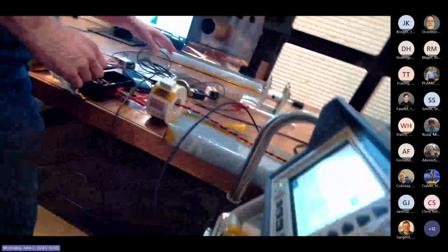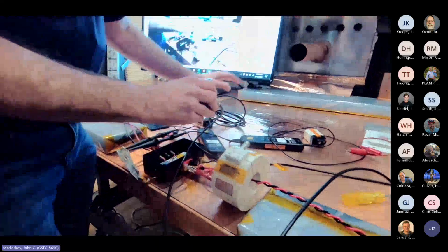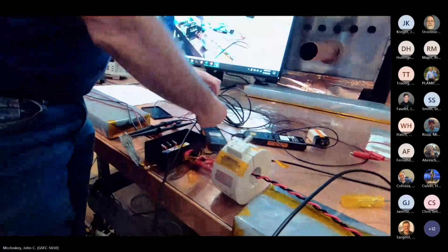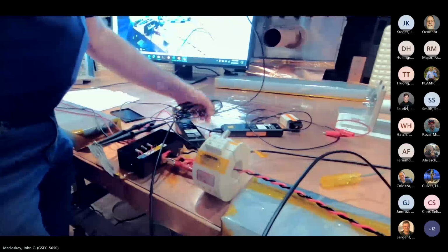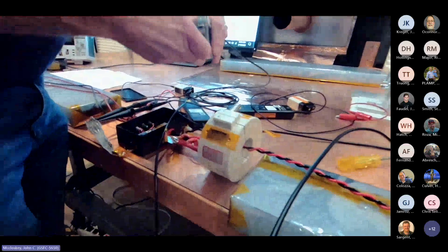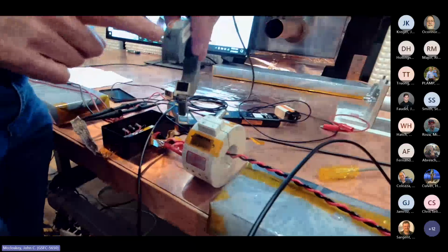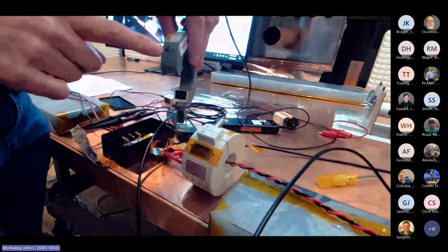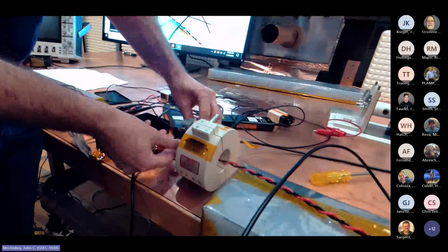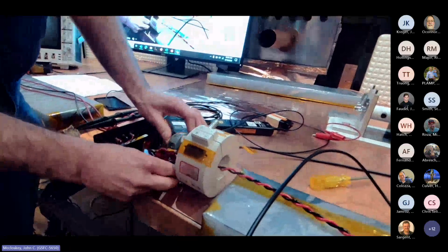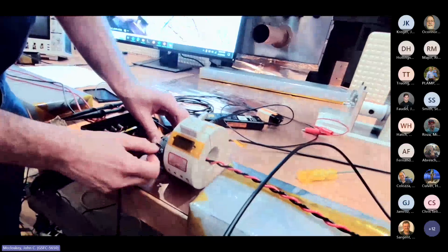Okay, and our input to the probe is connected to the signal generator still. The main thing we're going to be monitoring is our injected current. And again, this will be kind of a crude version of it with this simplistic setup. I do have an arrow marking the direction of positive current flow for whatever it's worth. Again, it's not terribly important for this, but if it's there, why not? I will have that going toward the EUT.